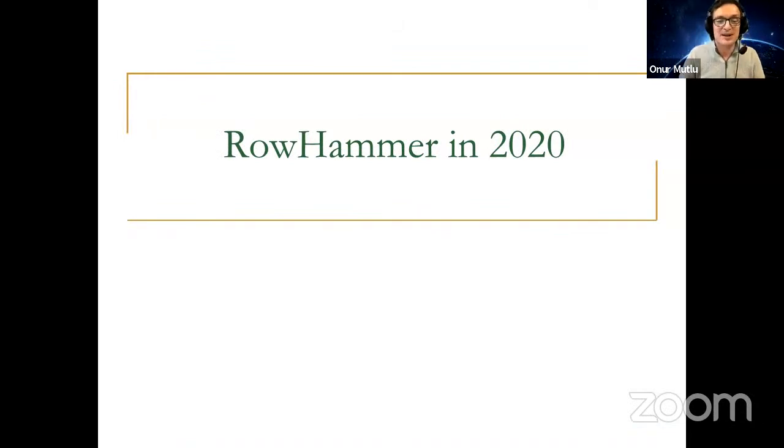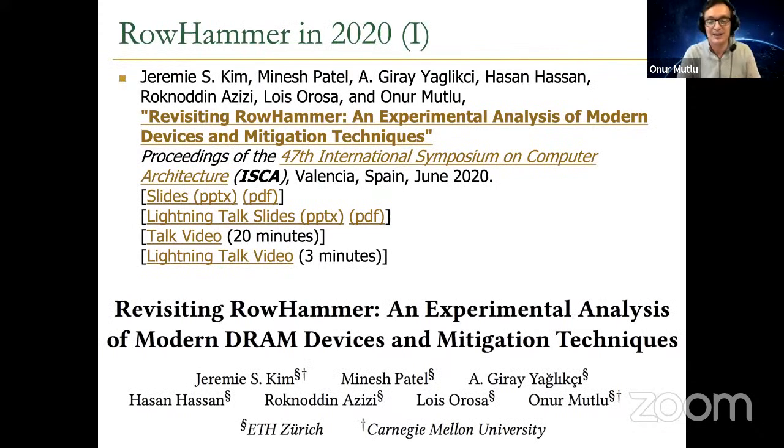We have written some papers that have had significant impact in the field, like this one, where we show that RowHammer is becoming much, much worse today. You can actually induce bit flips after only 4,800 double-sided hammers, which is really bad because in the first paper that we wrote in 2014, that number was 139,000. So there's a huge drop in the number of hammerings that you have to do to induce bit flips. So technology scaling is getting worse, basically.